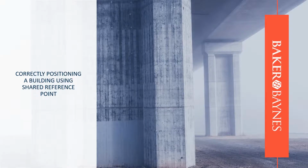Okay, now the fun part starts. Now we have a building that we want to correctly position, not only in Civil 3D, but also in Revit. What we pick up is generally the architects will do their design and they will model using the internal coordinate system in Revit, and that is not coordinated. Okay, we need to coordinate it to the civil model because the civil model dictates or governs the positioning. All right, so anything that you're exporting positioning wise, don't do it in Revit, do it in Civil 3D. It is catered for that. So let's have a look at what I'm actually talking about.